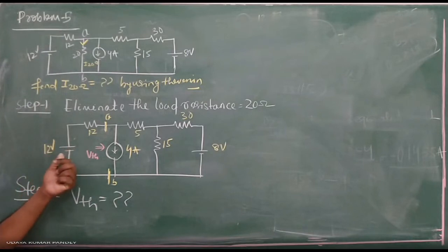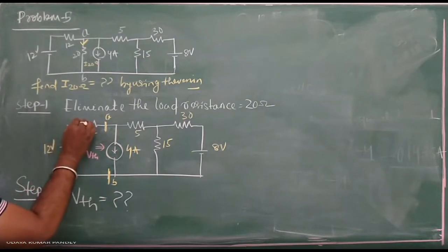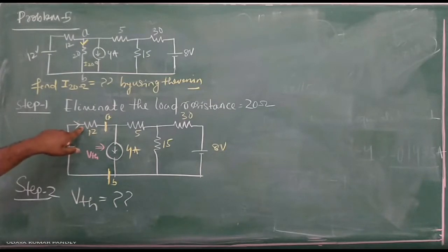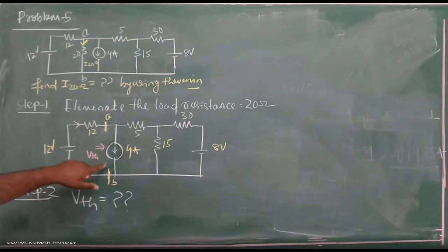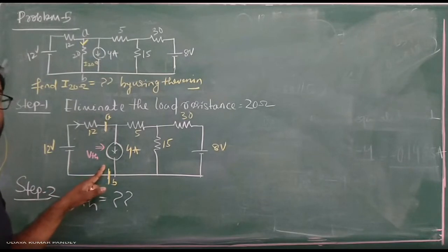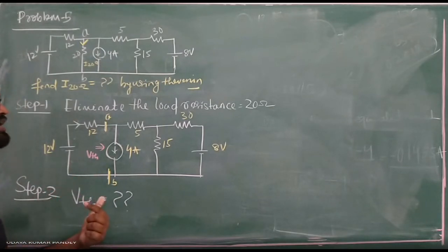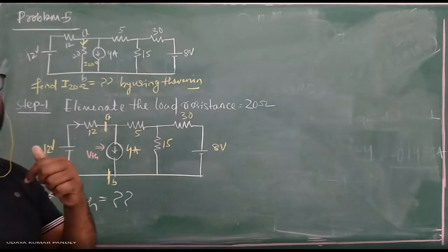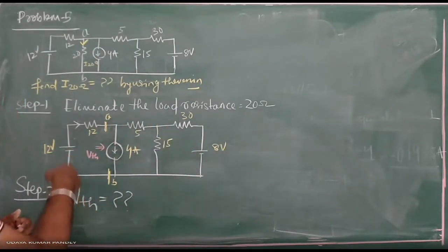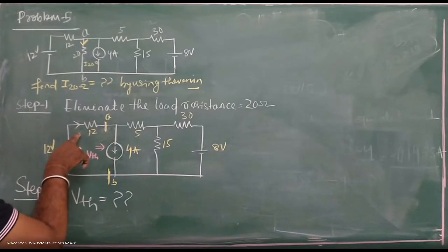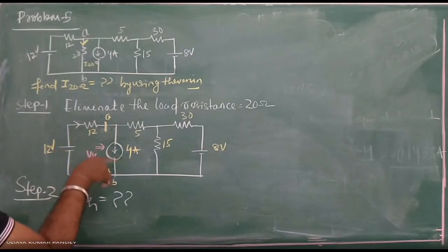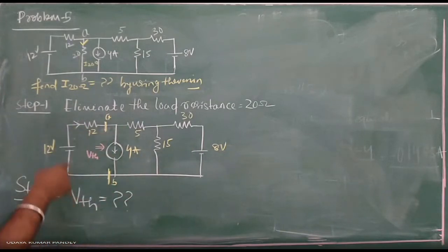Then before I am calculating this voltage, I have to calculate this current only. This current I have to calculate, this current or this current. Yes, sir. Okay, then how to calculate? You just see one thing. There is a current source given. Okay, then you have to use the same nodal analysis. I have to calculate this current only. Before I am calculating this current, I have to solve this circuit. Okay, then just put the nodes, and how many nodes here are possible? 3.